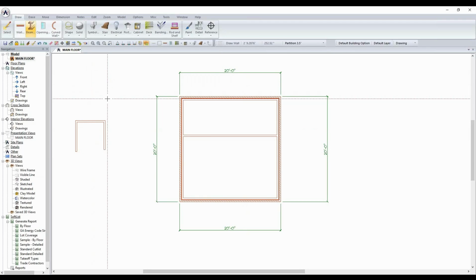Okay. There's 20 undos in SoftPlan, so hitting the backspace key is one of your best friends. Sometimes you'll just want to hit the backspace key and redo something. Remember that sometimes it's faster to undo and redo an item than it is to go and erase the item that you put in an error and then try and redraw it.